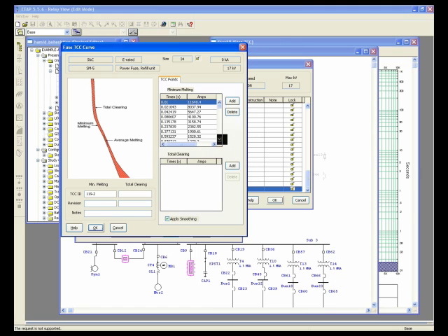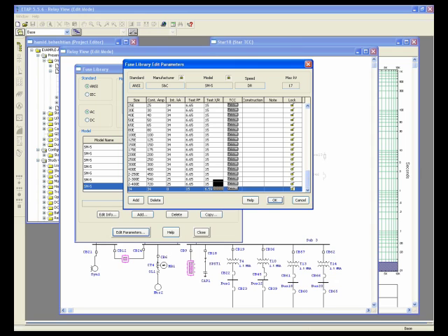Sometimes you don't put too many points, you just put a few points. So if you check this checkbox as apply smoothing, it's going to connect the points not with sharp angles, but just showing as a curvature. Okay, so by default I would suggest to put this checkbox as checked, so the curve in your TCC is showing as very smooth curves. So this is the very simple method to add the new sizes.